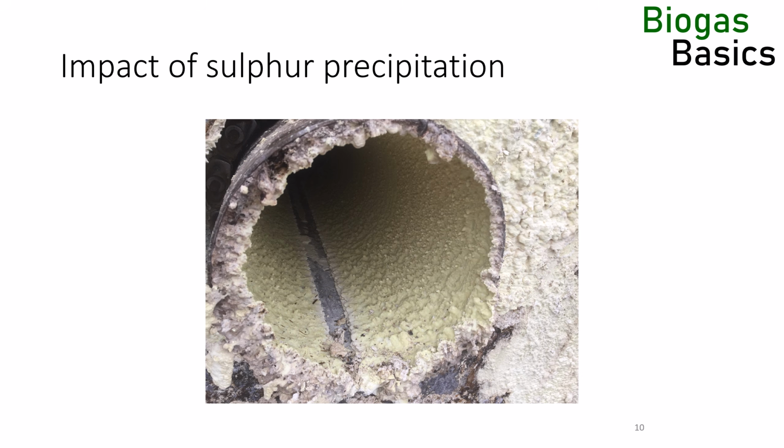One reason why pressure drops are almost always underestimated are sulfur precipitations in gas pipes. H2S will react with oxygen and water to elemental sulfur, sulfuric acid and biomass. A biofilm forms at the inner pipe surface, and it will be stabilized by elemental sulfur. The biofilm has an uneven surface. It creates local peaks and troughs, and the troughs will accumulate water.